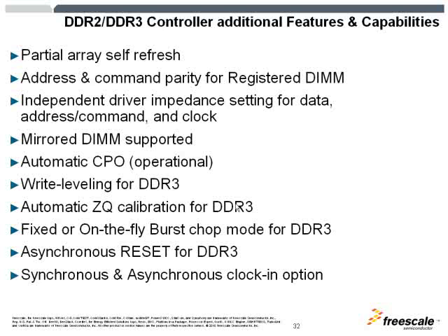And what you need to do is make sure that this reset pin is connected properly to a controller within your board to give you the capability to reset the DRAMs or DDR3s when you need to. And there's also a sequence that needs to be followed to be compliant per JEDEC. So you need to study that just a bit to understand that this feature is available, and it's a very good feature to take advantage of.